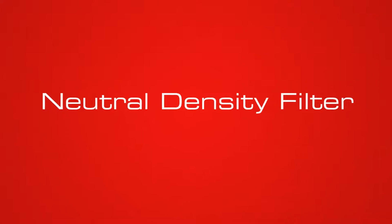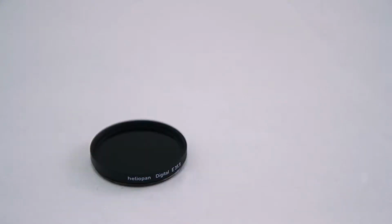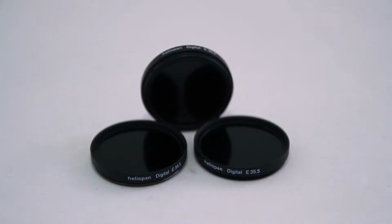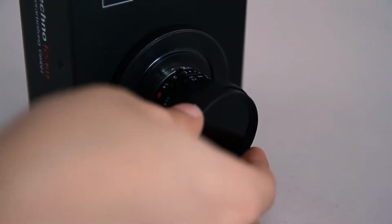Before capturing an image, the brightness of a scene to be captured can be adapted by selecting either a suitable exposure time or a neutral density filter. Neutral density filters enhance the measuring range of the camera in case of a very high luminance. Take the filter you want to use and mount it in front of the lens of the camera.